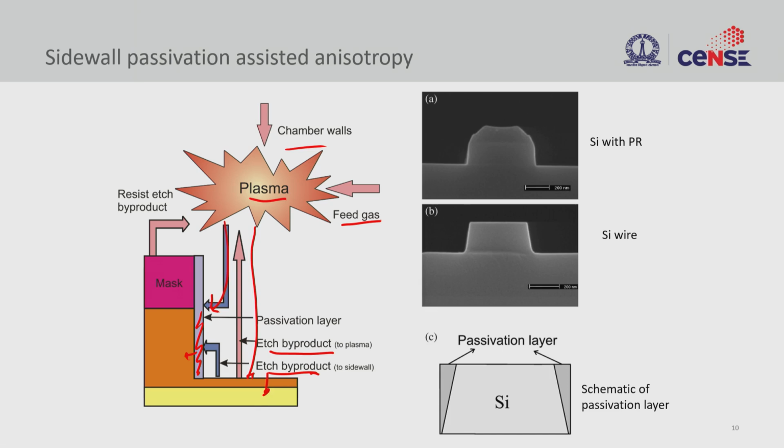And the resist is also participating in this whole reaction, right? The photo mask that we use, if the material can be etched with the plasma that we generate, ideally you don't want any reaction, but we never get infinite selectivity, right? So the material selectivity, let's say 1 to 100.